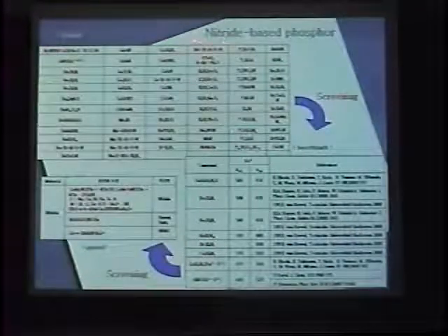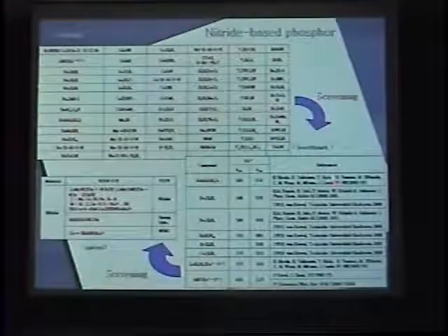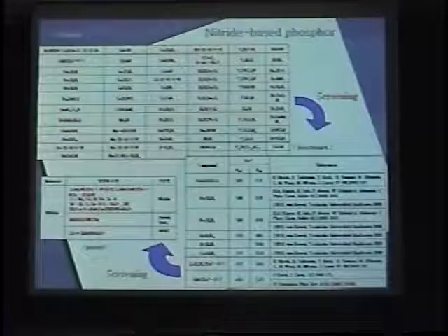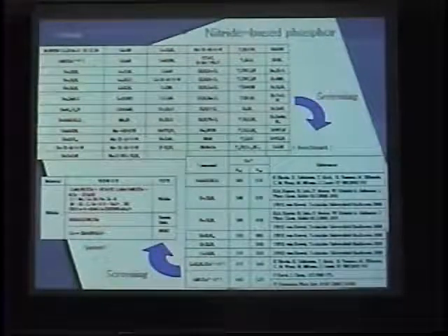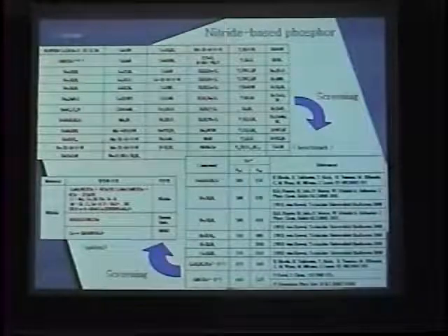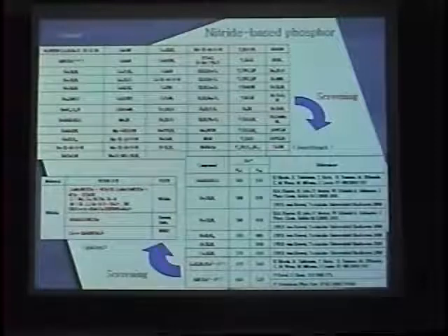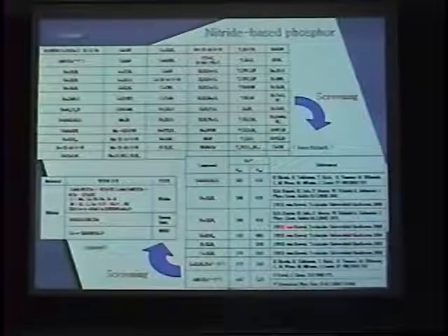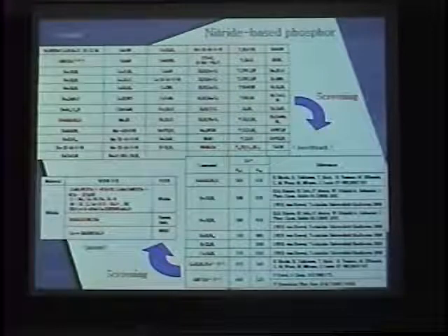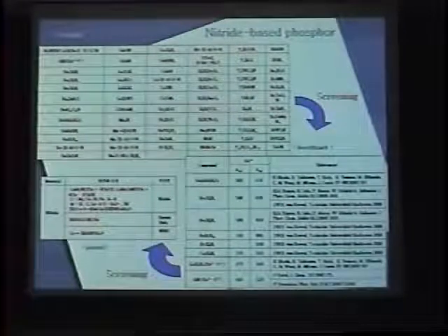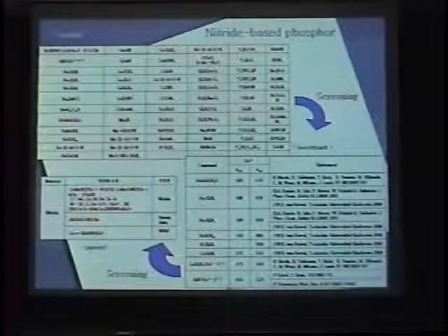This one, nitride phosphors, is a very emerging material. Usually in CRT or PDP, FED, many phosphors are oxide or sulfide based. But these days nitride is very important because it absorbs energy near the visible range, at 460 or even UV 405 nanometer.